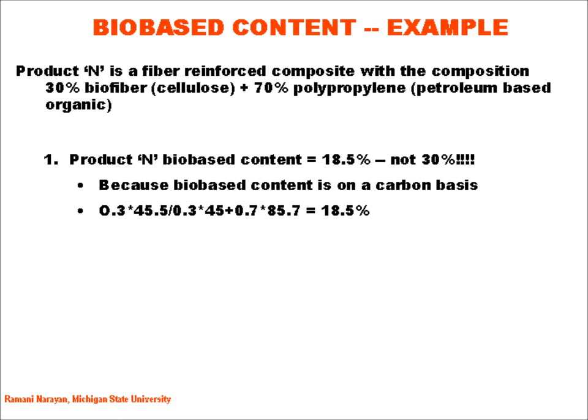All right? Let's put this into an example, which is what you have in front of you. Let's say you have a product N, which is a fiber-reinforced biocomposite, 30% fiber, which is cellulose, 70% polypropylene. On a weight basis, people will say, well, this is 30% renewable content, and many companies still do that. However, on a carbon basis, it is only 18.5%. Why? Because remember, it is on a carbon basis.